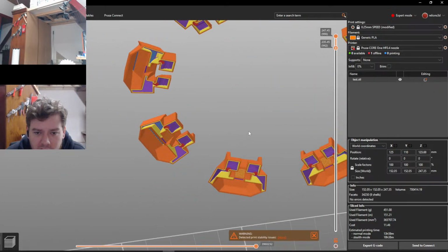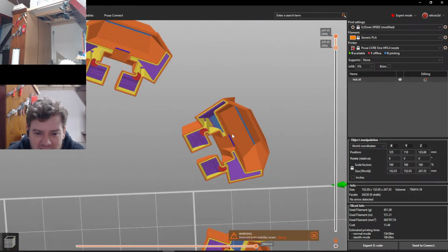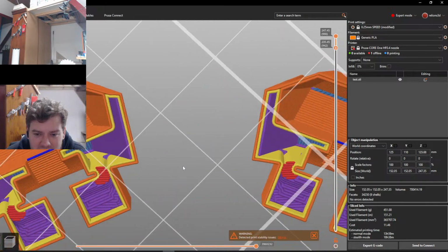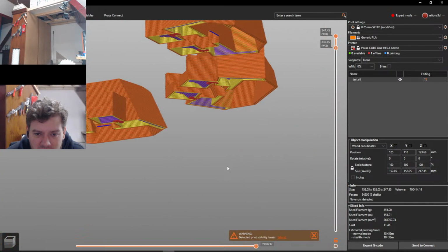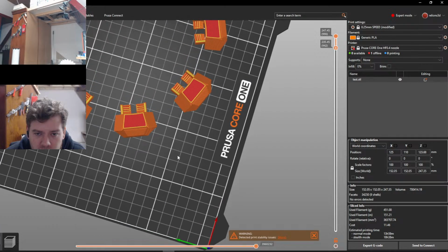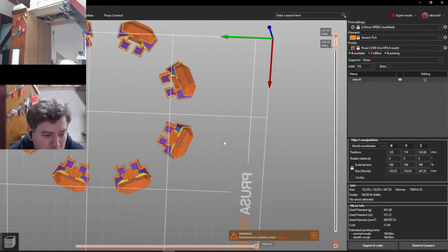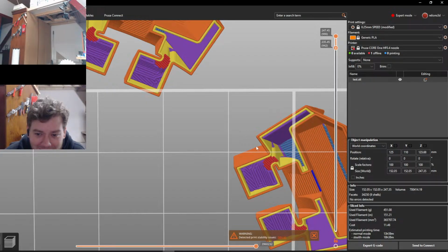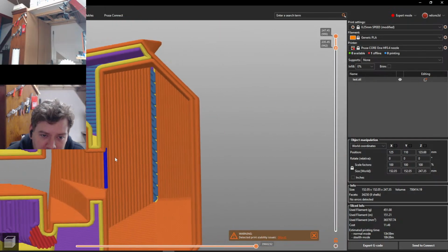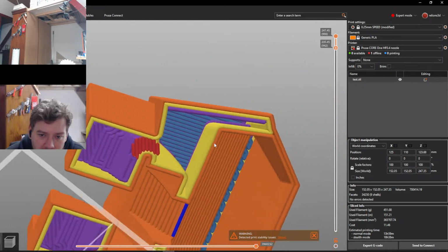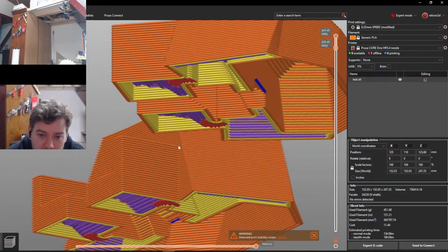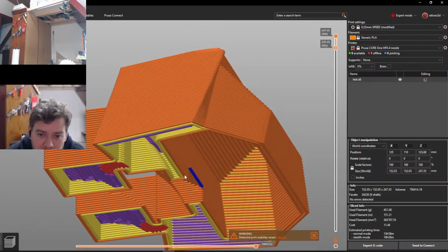That's really cool to think about. Can you actually do this without infill? Wait. Oh shit, you actually can. Okay, there's a small piece here, but I think this is small enough that you can bridge it. And again, you can make a small air pocket in here to make it bridgeable.